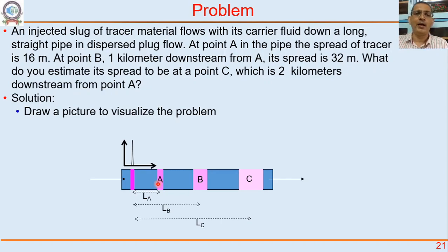That's why this pipeline problem is important. That is one possibility. This happens not just with crude oil, but whenever you are transporting materials having different properties in the same pipeline, and they mix with each other. Then we need to know how much is the mixed portion, how much is the spread of that material, so that we remove that material and reprocess it, and we get pure diesel and pure petrol.